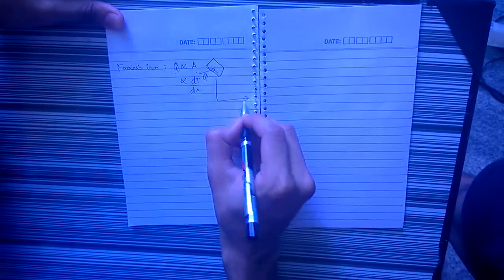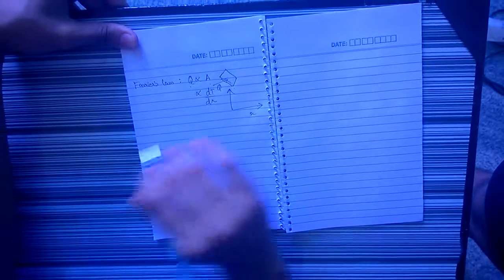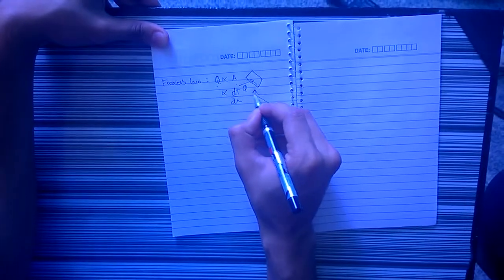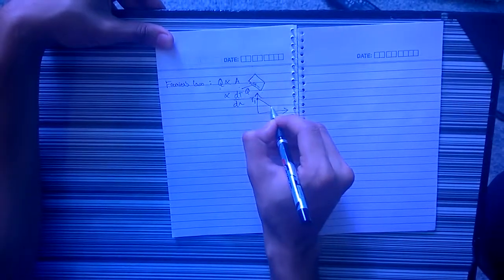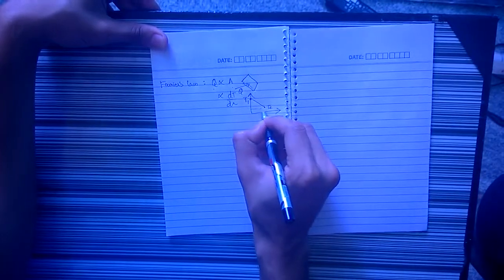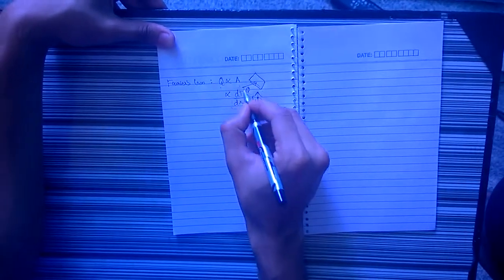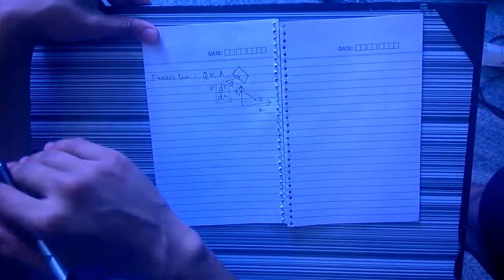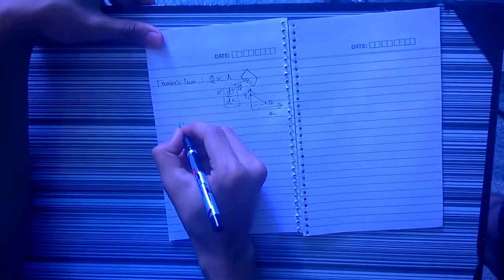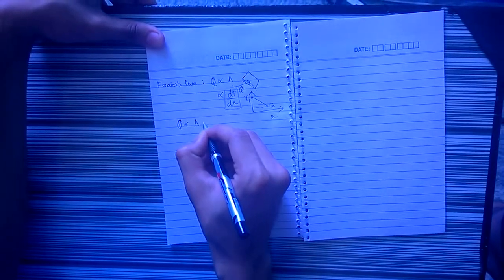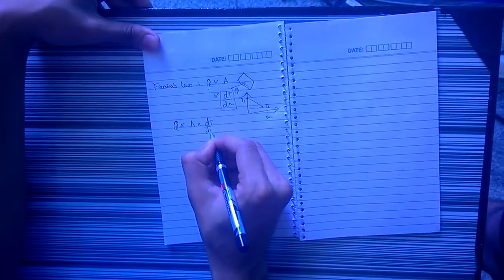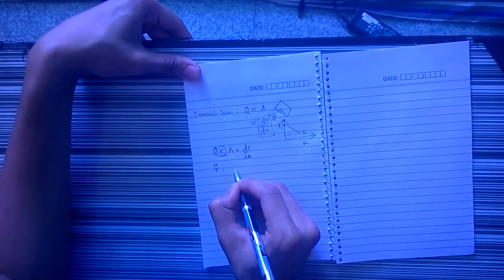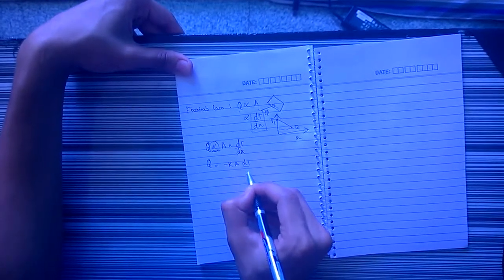So for example, if this is my x direction in which I am trying to observe, and this is the temperature profile, that is, at one end of the surface it is T1 and at the other end it is T2, then my heat transfer depends on the gradient, meaning slope. So it depends on the slope of how my temperature is changing in the direction of x. So we can write Q is proportional to A multiplied by dT by dx. Now to get rid of this proportionality constant, we have Q equal to minus K A into dT by dx.